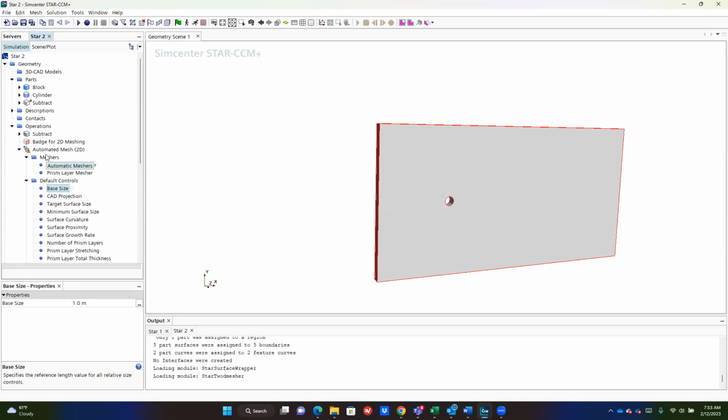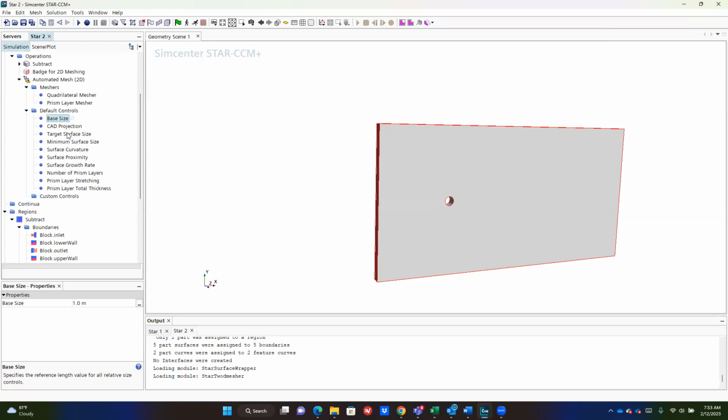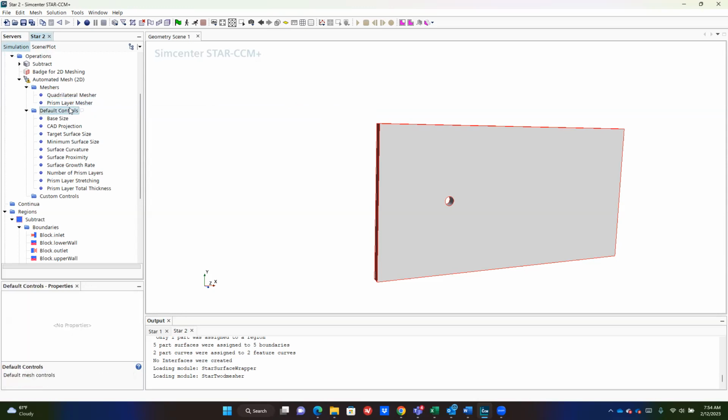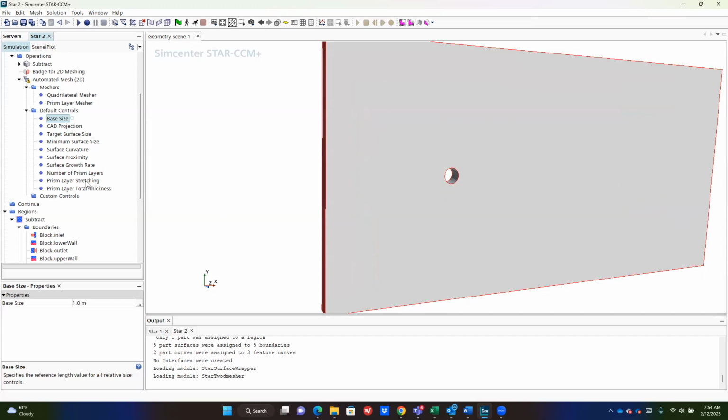Once you get to the mesh generation point, you have to select a couple of things. One, here's the basic settings for your mesh. Then you move into this mesh base size. This basically gives you a reference size for all the meshing. And if you change it, you can easily change between different mesh resolutions. We'll talk about that shortly.